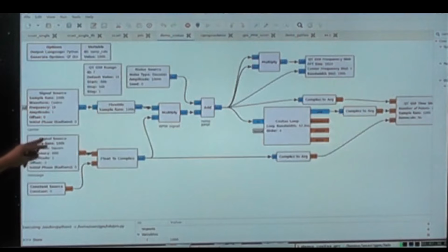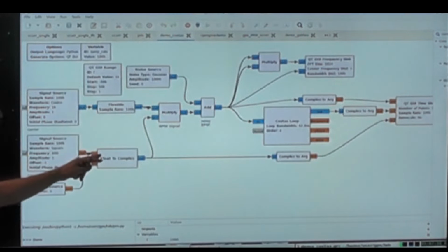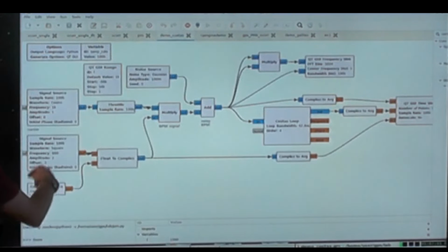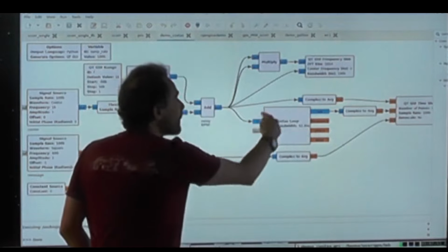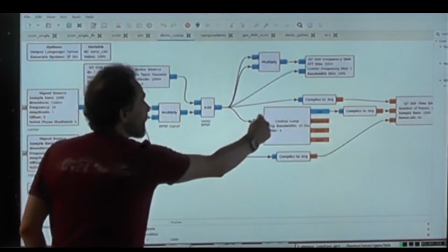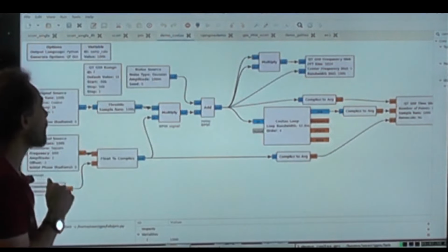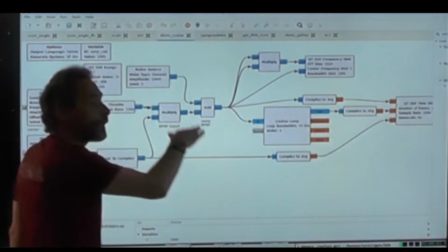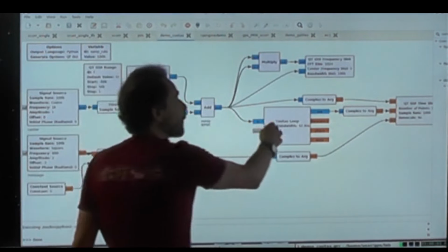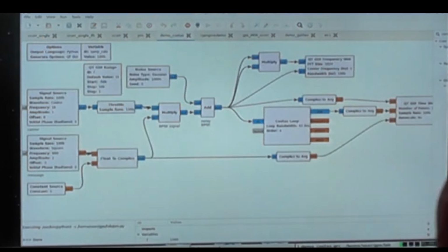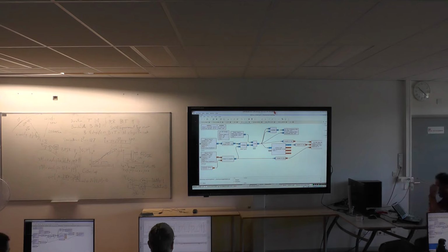On the bottom, I just took the square wave, and this square wave is what I actually want. This is a payload. This is what you want to recover. This is the message, the navigation message that was broadcast from the satellite. And on the middle curve, you will see the output of a Costas loop. So the Costas loop is receiving the signal phase modulated with a frequency offset, and it will detect the frequency offset, compensate for it, and give you as an output the frequency compensated signal without the frequency offset. So after compensating for delta f.